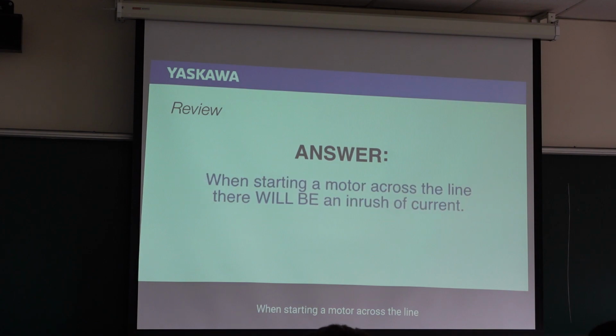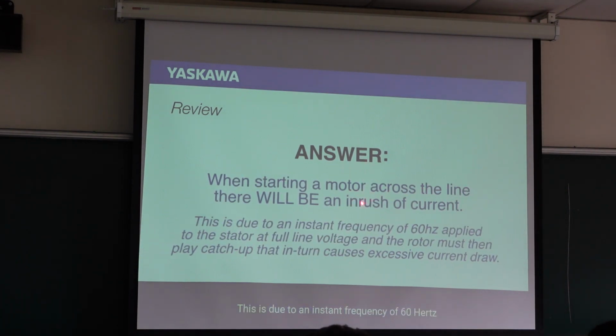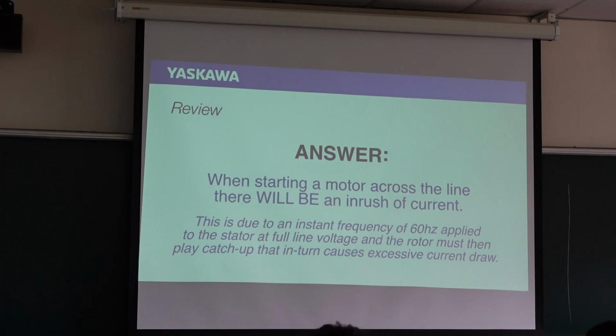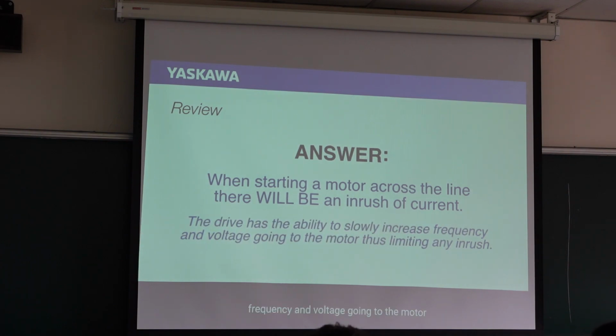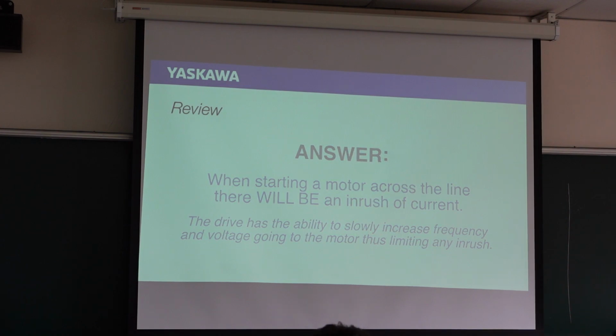When starting a motor across the line, there will be an inrush of current. This is due to 60 hertz applied to the stator at full line voltage, and the rotor must turn, which causes excessive current draw. The drive has the ability to slowly increase frequency and voltage.